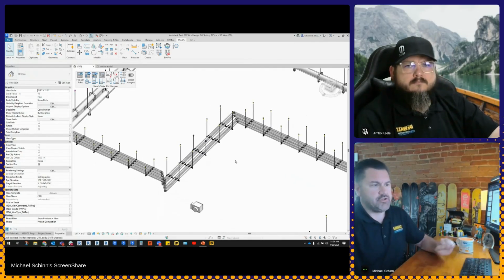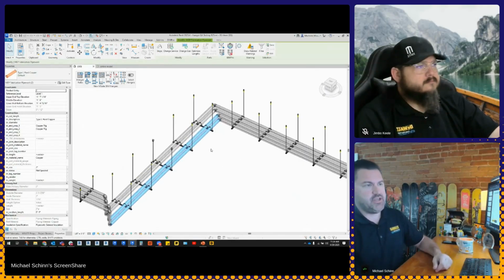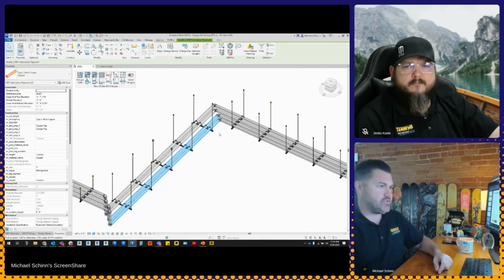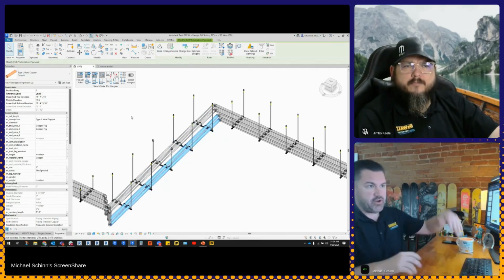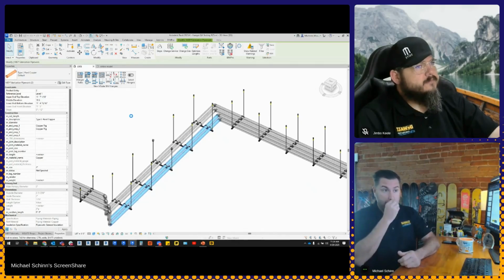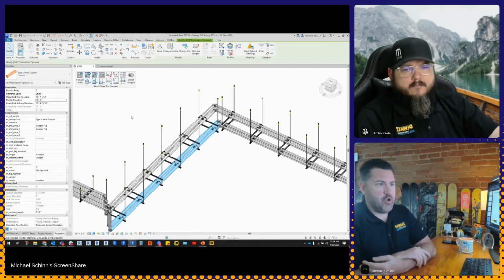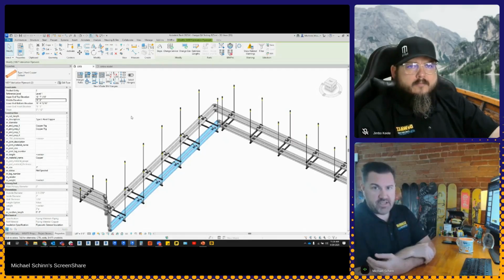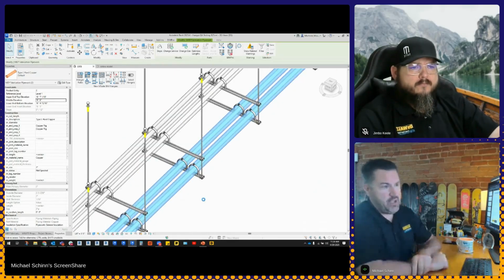Another problem is that usually, well, I don't like placing trapeze because I also have to be able to adjust and move things around. Well, I want to take these two pipes and drop them down to maybe 10'6" for whatever reason, for a coordination purpose. Well, then I want all the hangers to update to be a multi-tier rack. If I were to move that pipe over, I want those hangers to also update.